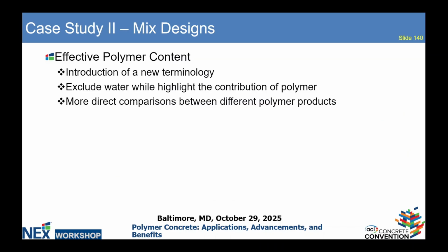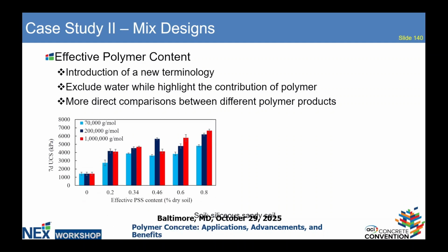And here is the concept that I talked about, the dosage of the polymer content. There are so many different terms in there, all talking about the same concept, which usually won't exist when you talk about other stabilizers like cement or lime. It's pretty straightforward. But in this case, to eliminate that confusion in the literature, between the different researchers or practitioners, we introduced a term called effective polymer content, which is not really new. We just want to say, hey, you guys need to express the polymer content in a better, more consistent way, so that everybody can understand how much material you put in the mix.